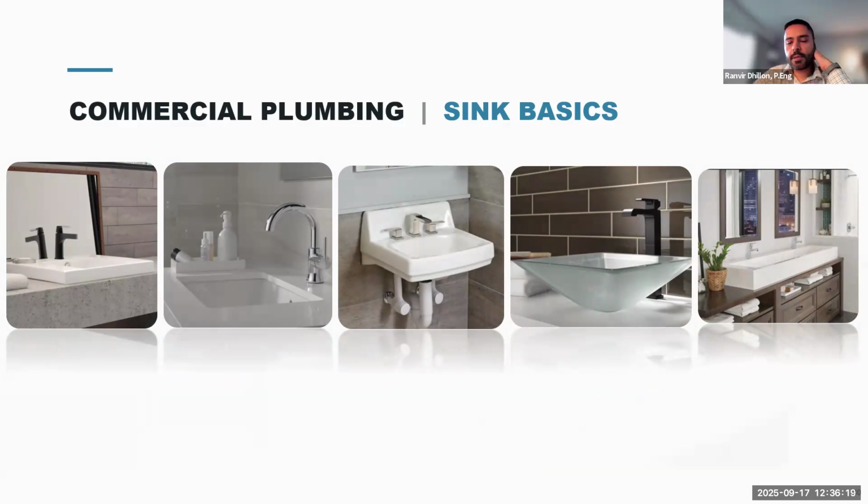So when you're selecting a sink for public bathrooms, consider both functionality and aesthetics. The main options to consider include the following. So for lavatory sinks, they can be drop-in. They all, of course, come in various sizes. But drop-in sinks are placed on a countertop surface and can be made of materials like ceramic or porcelain or even stainless steel. Then you have undermount sinks, which are mounted to the counter from underneath, so there's no lip protruding on the counter surface. So it actually gives you a little bit more counter surface and is more in vogue today in terms of popularity.